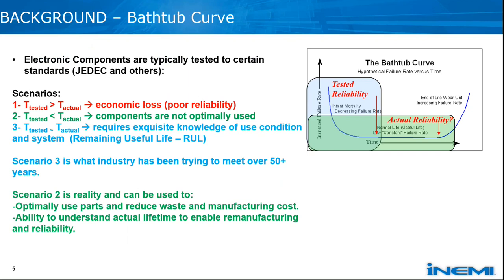So this is the typical bathtub curve, and due to cycle time and market pressures, the components are usually tested to ensure the elimination of infant failures and provide a reasonable estimation of the useful life. The end of life or wear out is rarely determined by the qualification testing done at the manufacturers. And plus the useful life will depend on the application conditions, and that limits the effectiveness of some of the manufacturers' testing, because in actual use the conditions may be severely different.